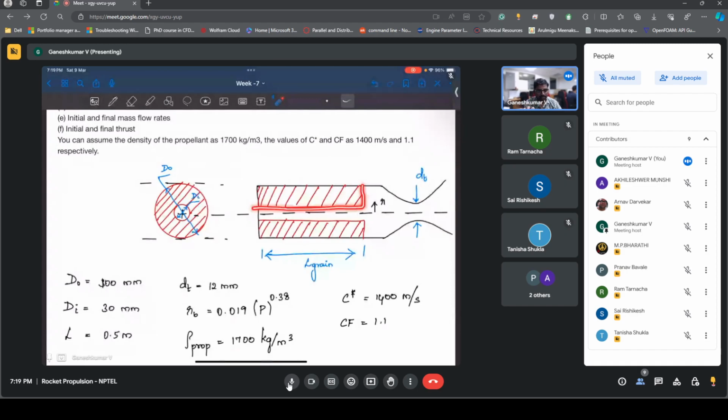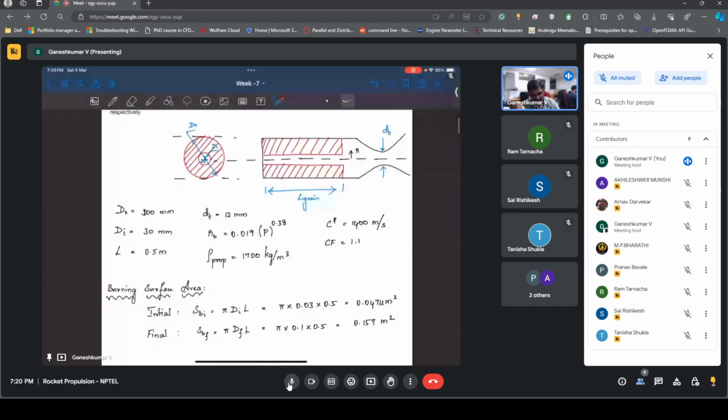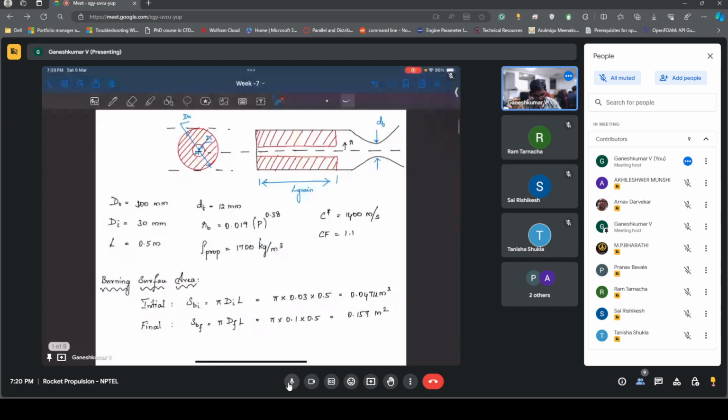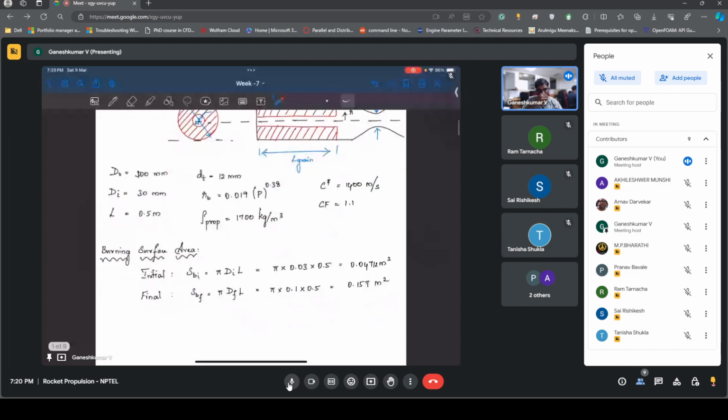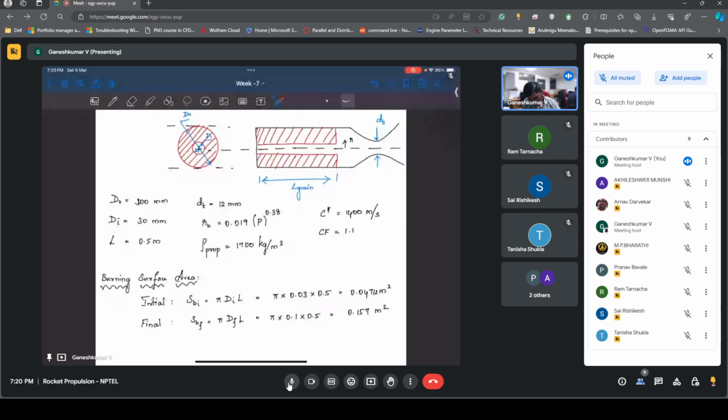There is no reason for it to not burn. But since we said it's radial burning, we are ignoring that surface. Once you ignite, the flame actually spreads everywhere on the surface, even to the side faces. Only if the inhibitor is there, you won't see this.